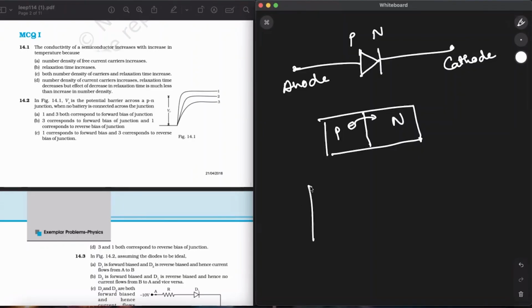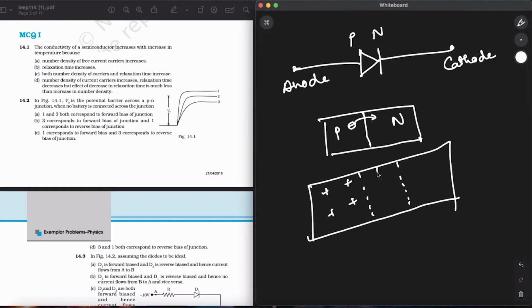So the depletion layer can be shown like this with a better diagram. This is the plus, plus, plus, plus. This is the junction. Minus, minus, plus, plus, and minus, minus, minus, minus. This is the n type. Since the electrons flowed from here to here, the holes that were here were filled by an electron, and the electrons which moved from the n type created holes in the n type. So there's a plus side over here. So the thickness of the depletion region is in microns.